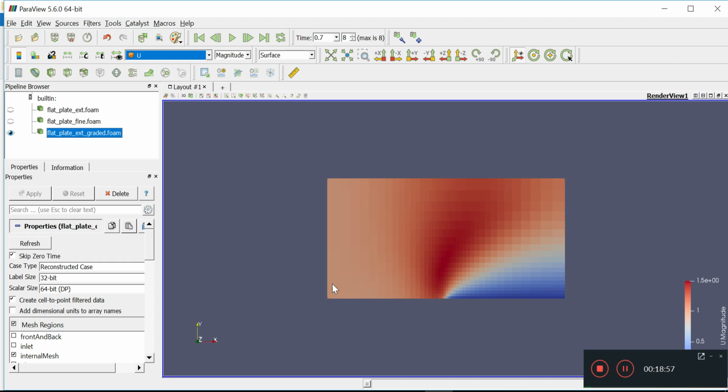So you see, when we get the expansion ratio right, this is what will result. Okay, it gives us a very high definition kind of picture while using similar computation time, except that it only increases because of the time step, rather than increasing the number of mesh cells to solve. So apparently, yeah, at least we got the grading right, and that's something for us to learn. But we still don't get the boundary layer flow that we really want. We're going to wonder what's going on.